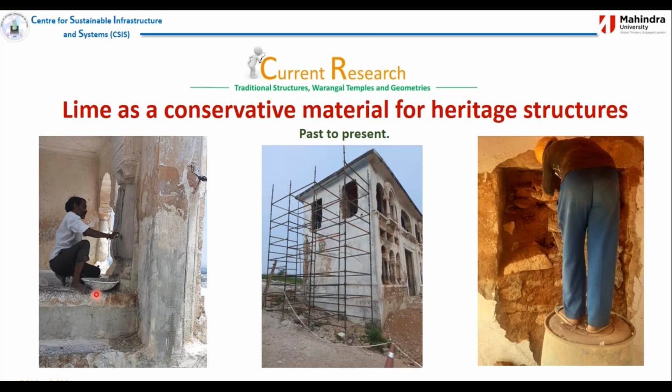So on this scaffolding, you can see the person actually using tapi. Tapi is just used for cement. So for actual lime, they use a jute bag to finish that, not the tapi. With tapi, we won't get exactly the finish.